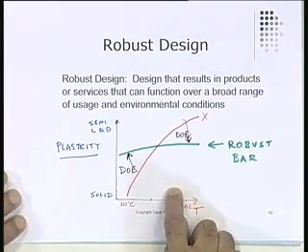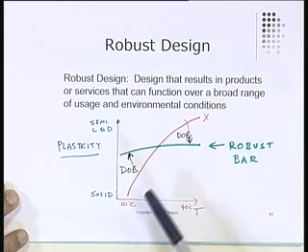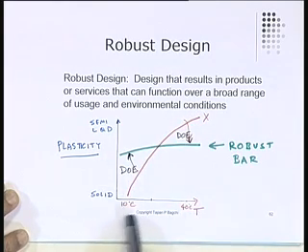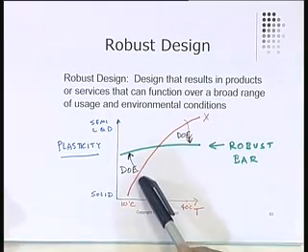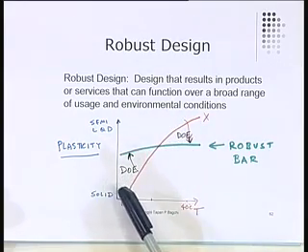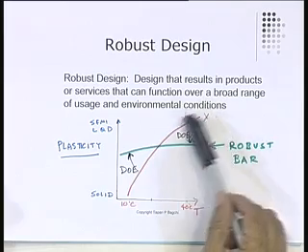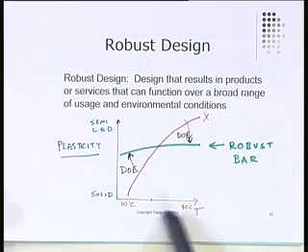In the case of what we manipulated, in the case of our robust design, remember this picture that I had there? This picture? Here, the design variables would be all the things that go into the chocolate bar. And this is my ambient factor. So what Taguchi said is, when you're trying to produce a robust design, do not only manipulate these design factors, but also manipulate this and look at the total response. Look at the total response, which is now the composite, and it is indeed the interaction of the effect of the design variables, and that of the ambient condition or the noise condition.